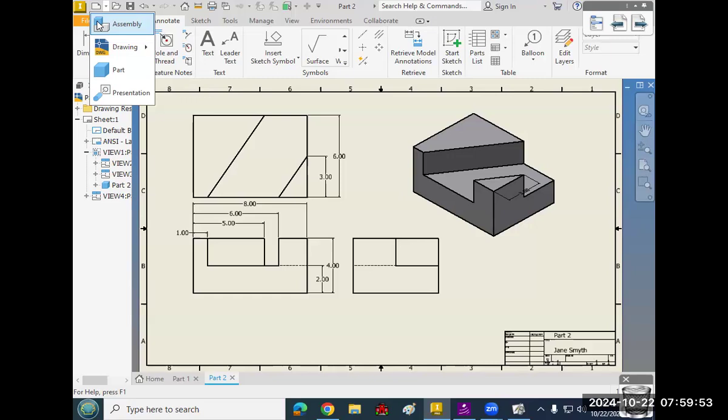It's referencing that part file. So even if you made a subfolder for the part files and a subfolder for the drawing files, they wouldn't really work. If you made it that way originally, maybe, but definitely not if you move things.